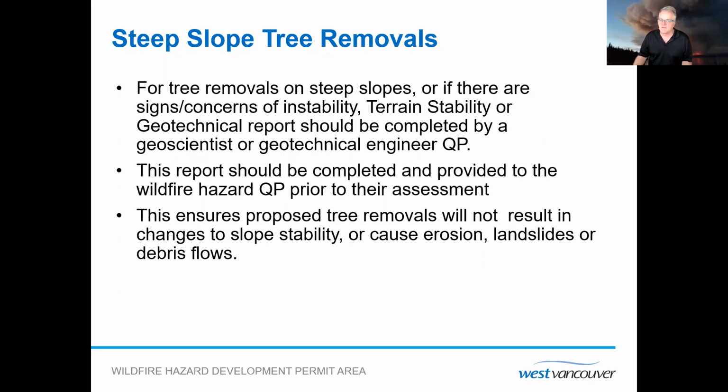And really, this is focused on maintaining the integrity of slopes and making sure that if the wildfire hazard assessment is prescribing some form of tree removal, that's not going to cause any related stability concerns as it relates to the property. This report should be completed and provided to the wildfire hazard QP prior to their assessment. And this really is focused on ensuring that tree removals will not result in changes to slope stability, cause erosion, landslides, or debris flows.